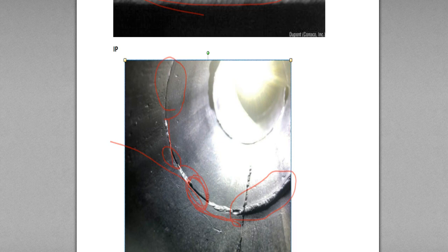So here IP number 1, here IP number 2, IP number 3. So you just measure. This is not IP. This is not IP. Here is IP number 3. So measure the sum of IP number 1, 2, 3. If this exceeds 25 mm, this is reject. Only this kind of question comes up in the CWI Part B actual question.